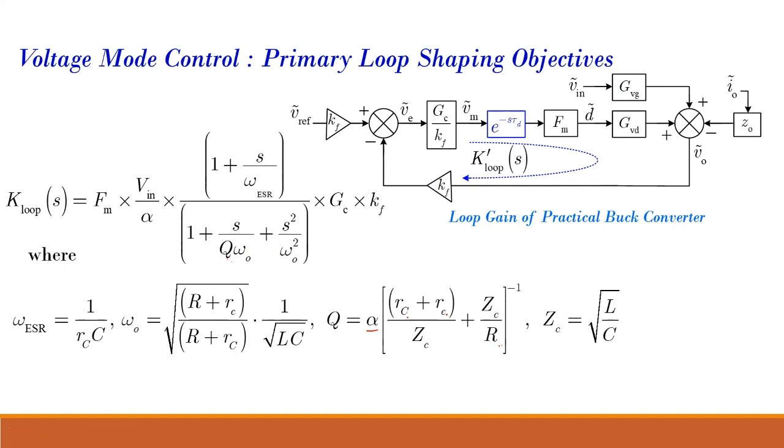Sir, actually in our basic circuit, if you take RL, the physical significance is that if the Q factor is high, then the inductor is closer to a pure inductance. That is for the inductor. So similarly, what is the significance of this Q? See, that is a first order system because it has only RL. And that quality factor is basically how low the resistance of the inductor is.